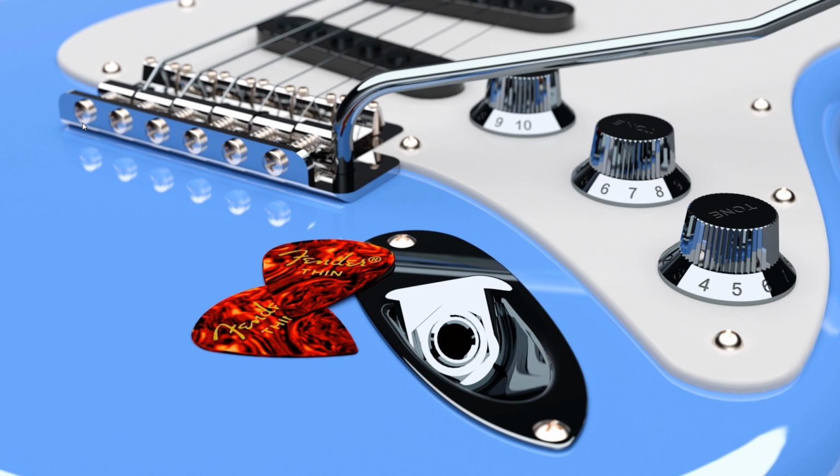So what I've done here, the other direction actually is like a 70mm or something like that. That would give you a zoomed in effect, and that's what I chose here for this image. I chose to position my model, and I chose a 70mm zoom lens for the focal length. And then I set the depth of field to a value of 8.